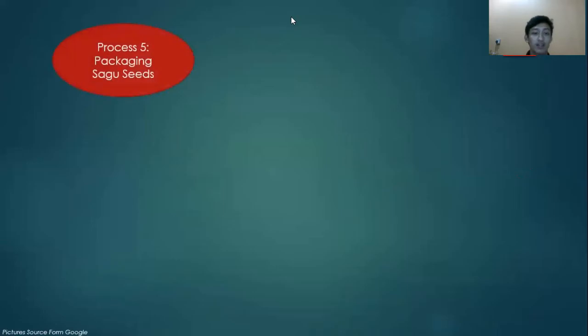Finally, the sago seeds will be packed into a suitable size of packaging. A ZV320A automatic filling packaging machine by Cortem can help in packaging the sago seeds, as it packs from a range of 50 to 500 grams of packaging size, which is a common packaging size for seed and snack in the market. This will help us to pack the sago seeds faster and more accurately, as the filling process has been aided by the computer control system of the machine to fill the sago seeds into the packaging.